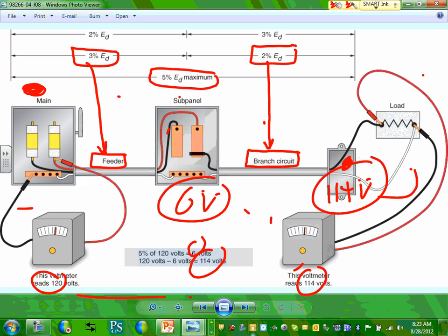And what happens with this one? If it's less efficient, it consumes more power, and it will also die prematurely because it pulls more current to compensate for the loss of voltage. That's why almost all equipment is rated plus or minus 10%. The manufacturer typically rates them plus or minus 10%, so if you give them 10% more or 10% less voltage, they function. This is their range of functioning properly. Go higher or lower than that, and they can malfunction.